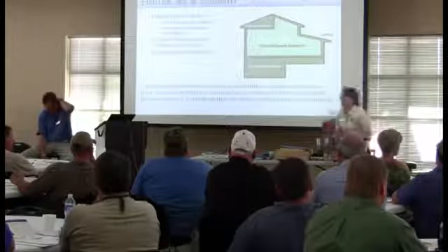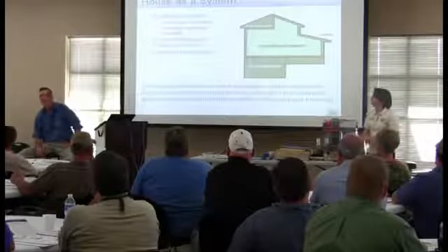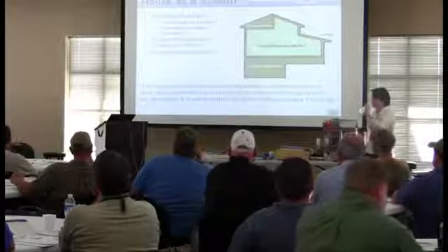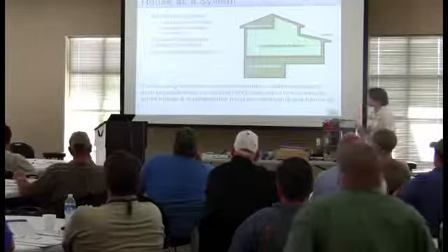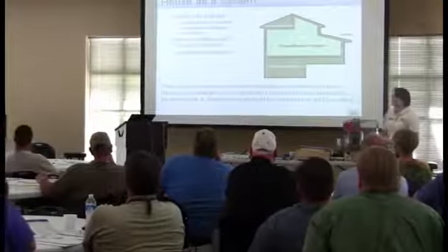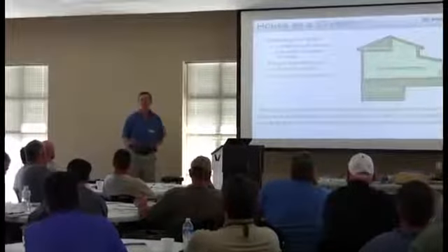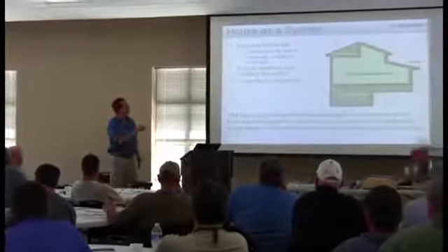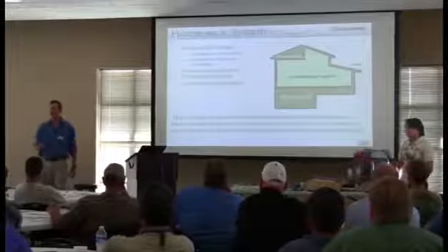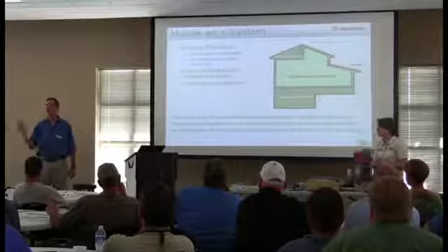But that's why in the energy code we don't actually see ventilation yet. But maybe. It's kind of interesting because I know a couple folks here work in the commercial world. In the commercial world, you have to do a good job on the building envelope, you have to do a good job on the mechanical systems, and you have to bring in outside air. All three of those are the law, in essence. They're all code requirements. But on homes, it's kind of funny, because you have to do this and you have to do this, but when it gets to the third bullet down there, only 5 out of the 50 states actually require intentional ventilation, and Georgia is not one of them.